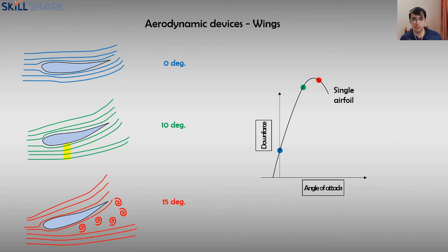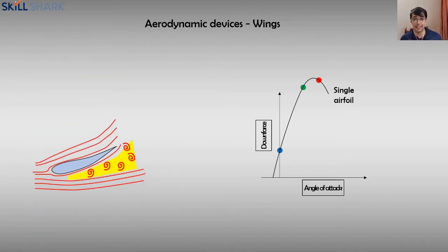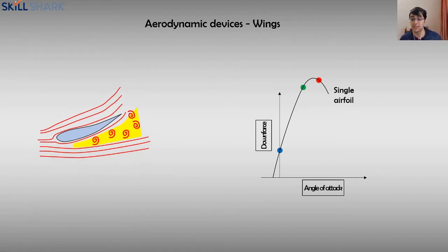So these two turbulent airflows collide, and it creates a sort of high pressure zone over there. So air becomes disordered, but it's not fast enough to create low enough pressure. So depending on the pressure differential, you're either going to have less downforce or, in really bad cases, lift, and you don't want that. So this is called the stall angle, where the airfoil stops performing because it stalls.